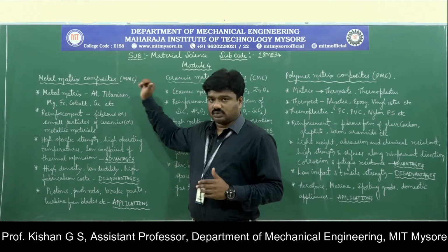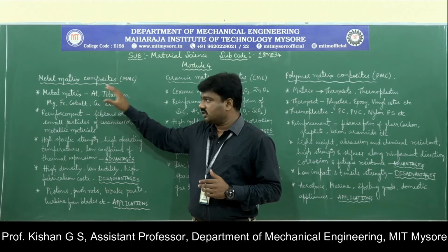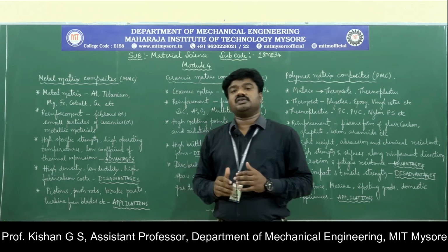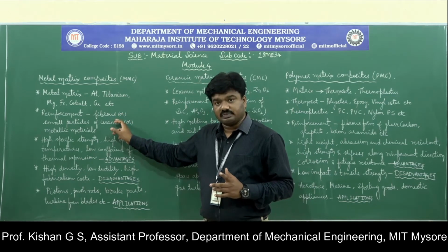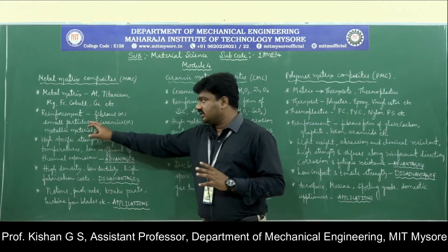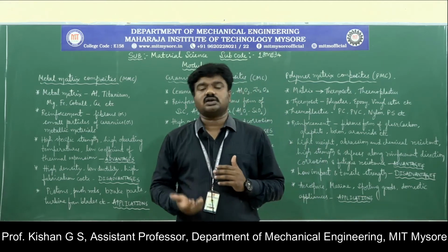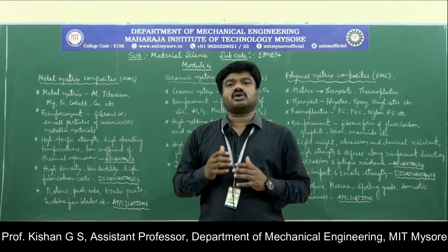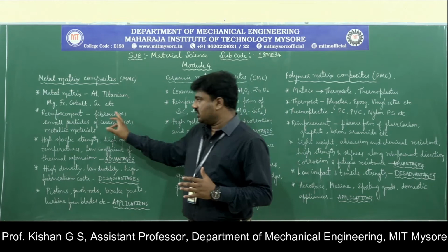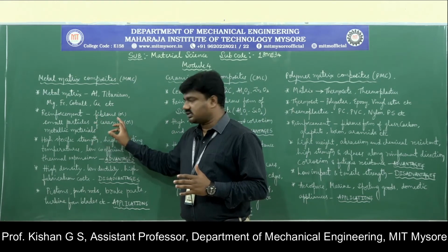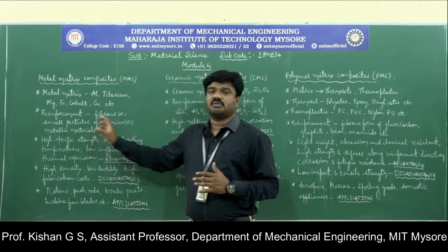So these are the materials which are generally preferred as metal matrix materials when we concentrate on metal matrix composites. So here, once we have these materials as the metal matrix materials, then what are the reinforcements? The preferred reinforcement for metal matrix composite should be fibrous in nature, or fiber reinforced composite material, or small particles of ceramics, means to say that it could be fiber reinforced or particulate composite materials, or a combination, once we develop the metal matrix composites here. So the nature of the reinforcement should be fibrous or small particle type, but the preferred materials are ceramics and metallic materials only.